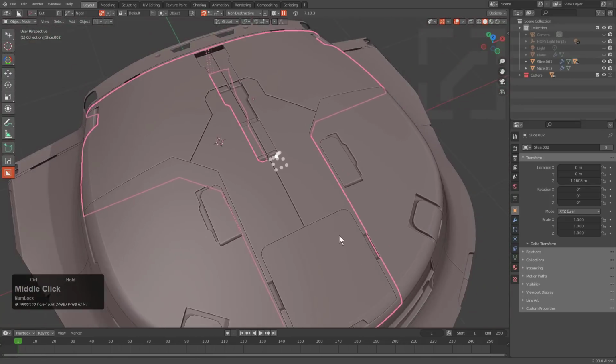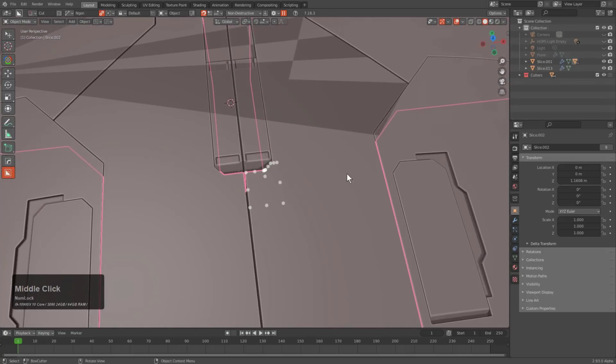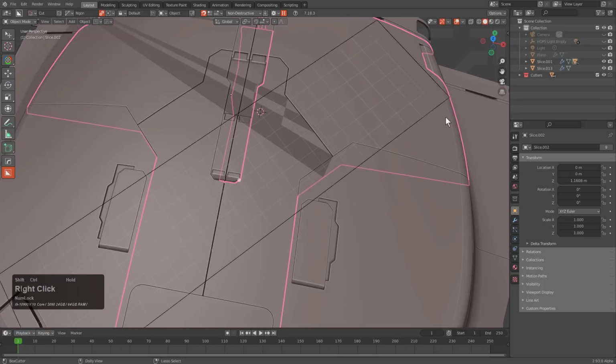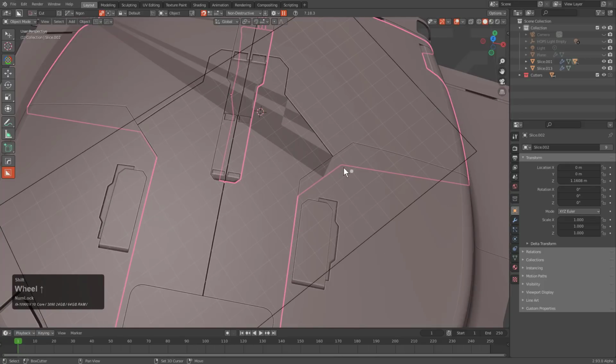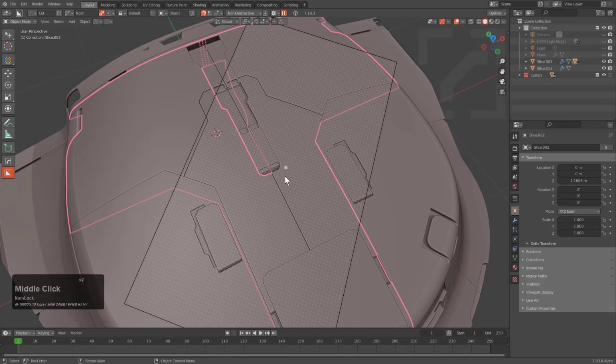We're able to zoom in and out because as of now, Boxcutter has 3D dots. Previously, there were 2D dots, which were deemed incompatible with our 3D grid. And we're able to just hover over each dot, seeing what potential alignment point we're being given before we even begin drawing. And if we want to expand this into something more static, like static grid, we could just hold control, roll the wheel, roll this grid into place, playing off of the angle that we chose, just extend the grid out however we'd like, shift, roll the wheel in order to bring it out, and here we are able to rock and roll with our grid.